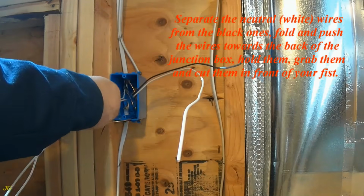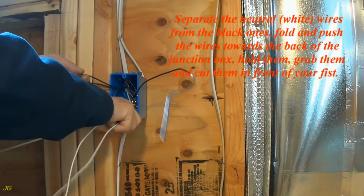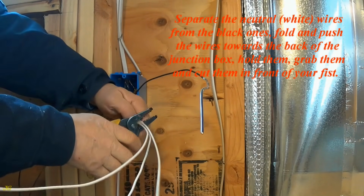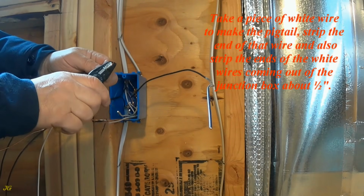Separate the neutral, white, wires from the black ones. Fold and push the wires towards the back of the junction box. Hold them. Grab them and cut them in front of your fist. Take a piece of white wire to make the pigtail.